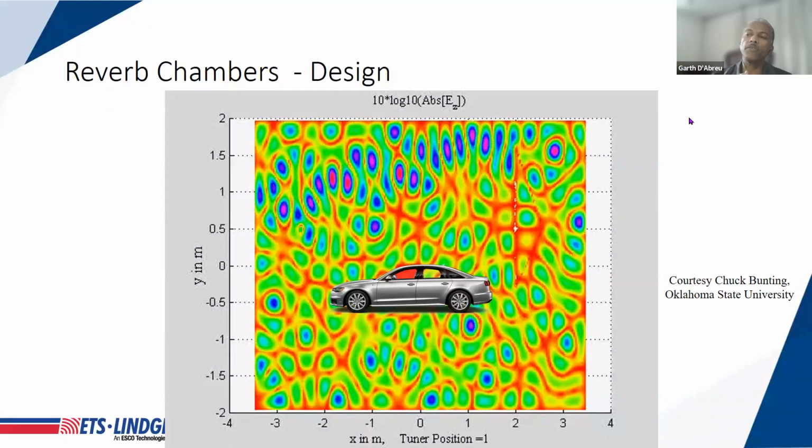Everything that ranges from the flexible fabric tent, the VERC, the vibrating chamber where you shake the walls of the facility to stir the modes, through the traditional rigid metallic box with rotating mechanical stirrers, including metallic boxes with moving structures, moving walls as the method of stirring the modes. A lot of different techniques are introduced.